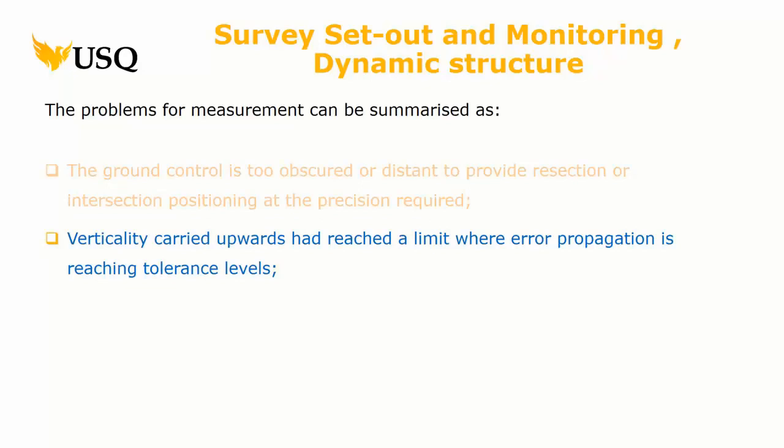And also, if we go back to that diagram, if we set up a laser plummet, right, even though it's all laser and digital, it's going to be vertical like that, even though the floor is like this. You know, because it finds true vertical. You got to remember, on the Earth, we're lucky with that, is that gravity is something outside our control, whereas angles are just all relative. That's nothing fancy. There's no such thing as a true angle. It's just a measure between one point and another.